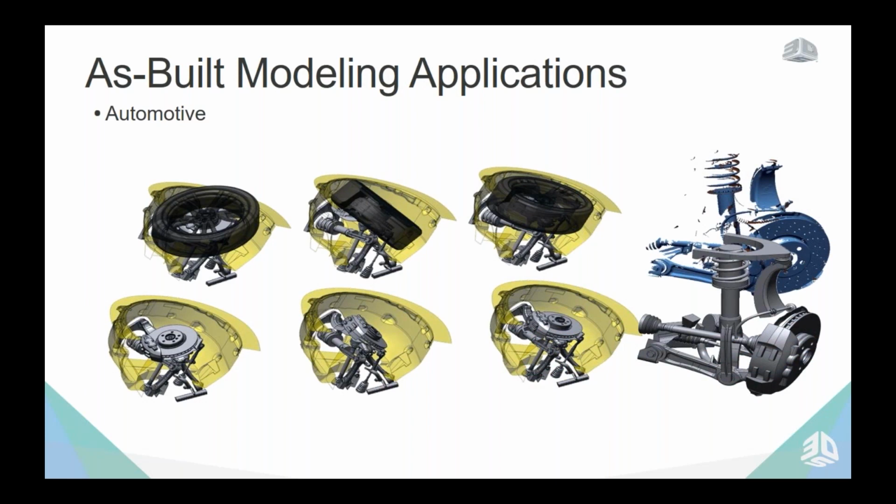Another application in the automotive industry is simulation for vehicle wheel travel and suspension. We did some very high accuracy modeling of the inner fender well of this vehicle, and also some feature modeling of the suspension and braking components, to make sure that not only did a new aftermarket wheel and tire package fit onto the existing hub and around the suspension components, but also inside of the wheel well here.